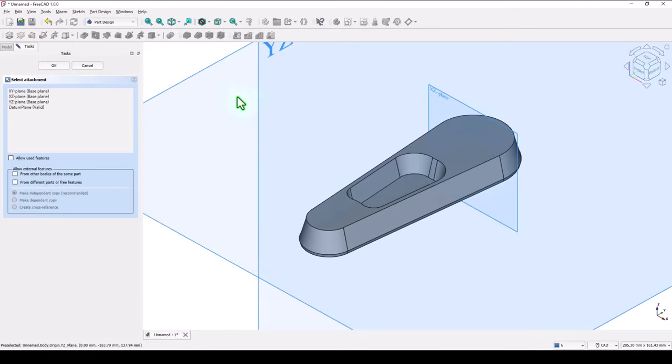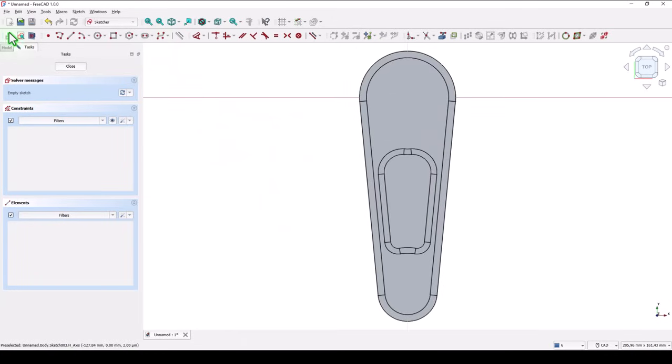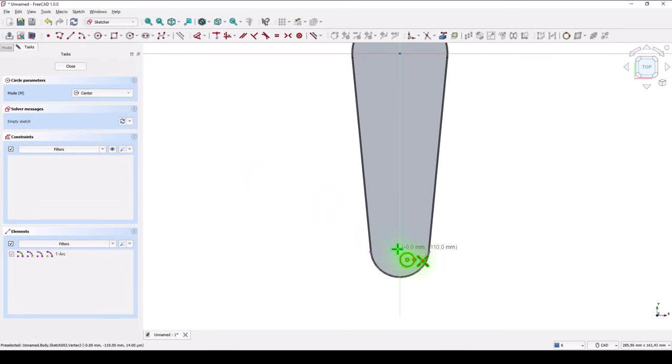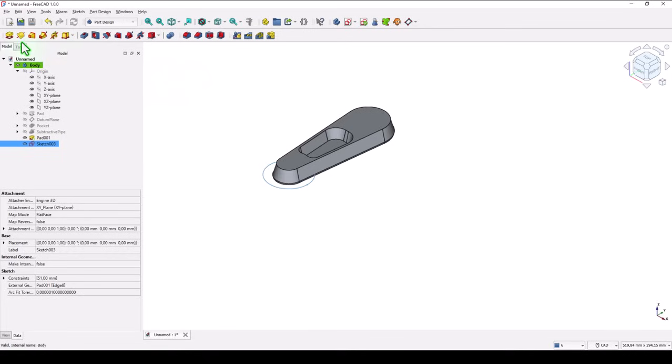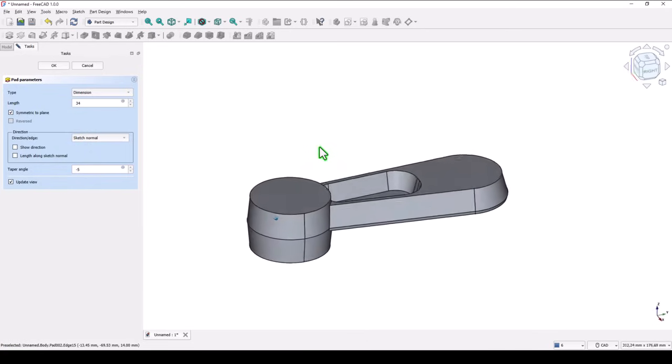We select the plane XY. For the other problem we have, inside project this arc to have a center, then a circle diameter of 51, close, extrude or pad, symmetrical on 34, and what is this? And the taper angle of minus 5. Okay, good.